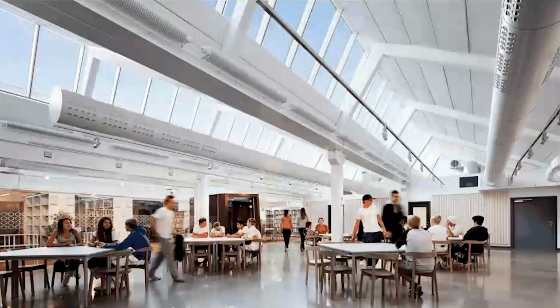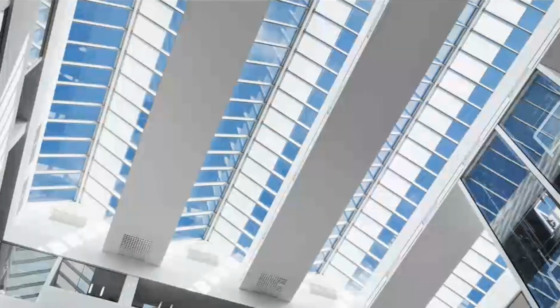And this is really common. This is a school project that you see here, but this is really common in warehousing in Europe, and is kind of a traditional way to do daylighting. You see it occasionally in North America, and I can say that we do have an exciting project coming up later this year where this is designed in. So I don't want to say any more about that, but it is still something that's being considered now for North America, and it's a great strategy for reducing solar heat gain.